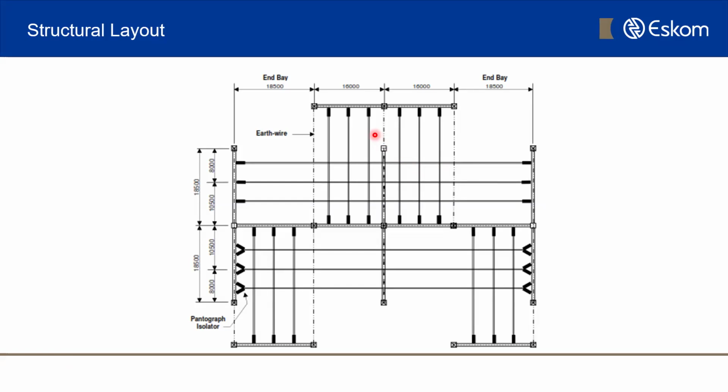Okay, and this is going to be the focus of our discussion today. This is the strung type. The rigid bus bar is very similar setup, except that it does not use gantry structures. Each tube is then carried by its own post-insulator system, as you might see later as we go through the presentation.